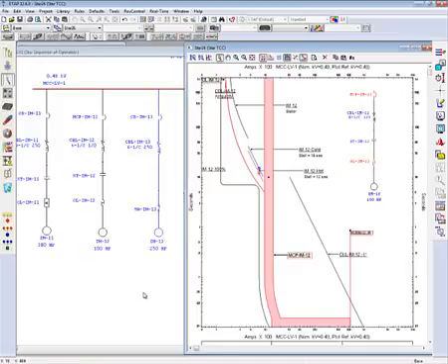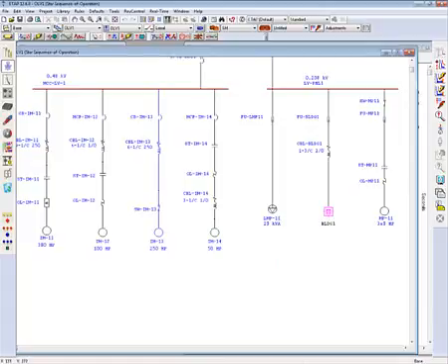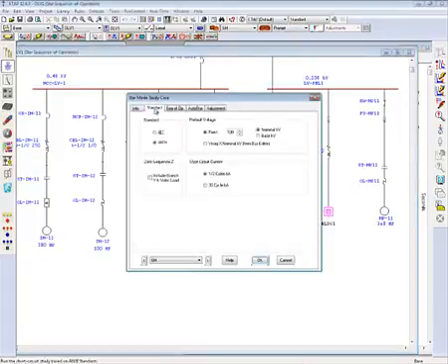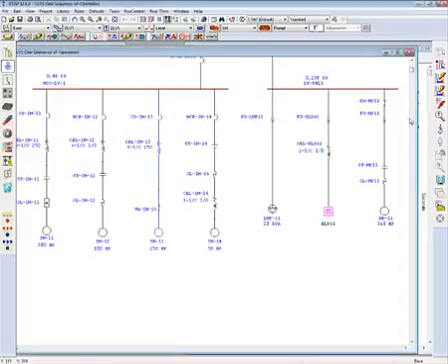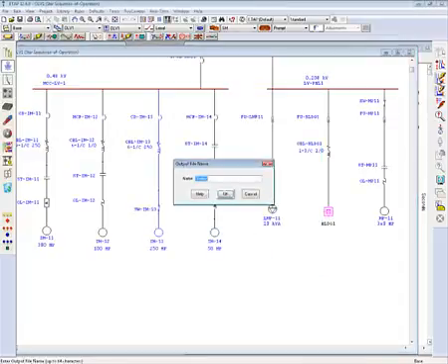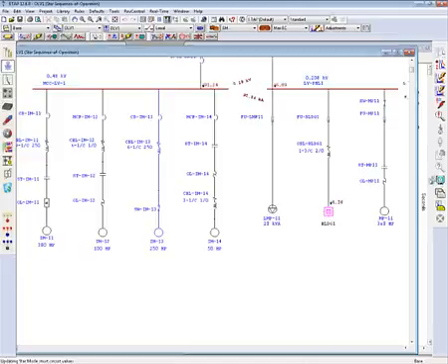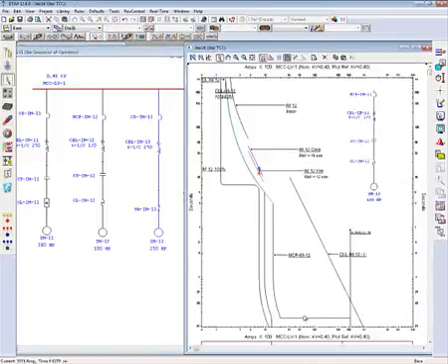So if you are in the star mode and you select to run a new short circuit study, based on the standard selected and the short circuit current type selected, half cycle for maximum current and 30 cycle for the minimum current, and you update the short circuit, you will have your fault markers for the connected protective devices.